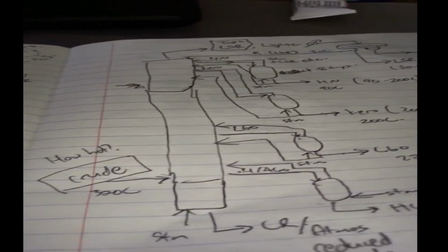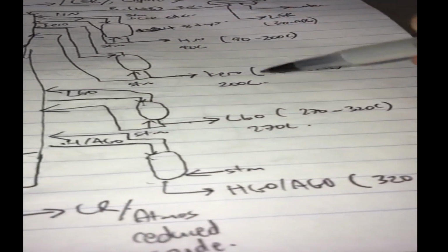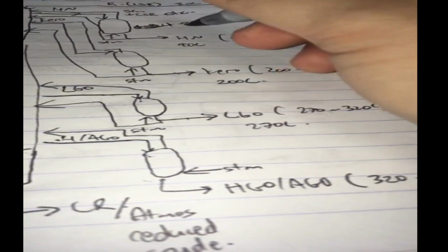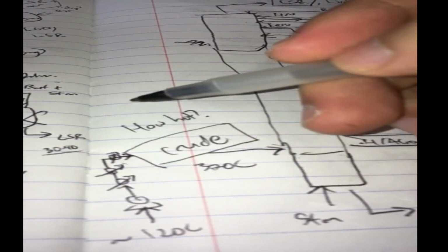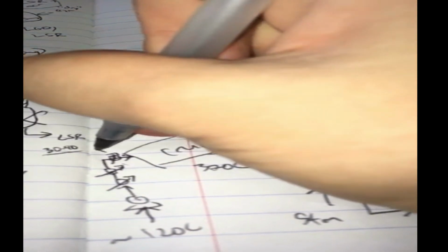So in conclusion, our atmospheric tower will look something like this. After coming out from the desalter, I'll have a pump. I'll have something known as a preheat train, where my crude oil actually goes through a heat exchange with each of these fractions to heat it up, and the remaining bit, you just burn some gas or burn something in a furnace to heat it up to about 370.